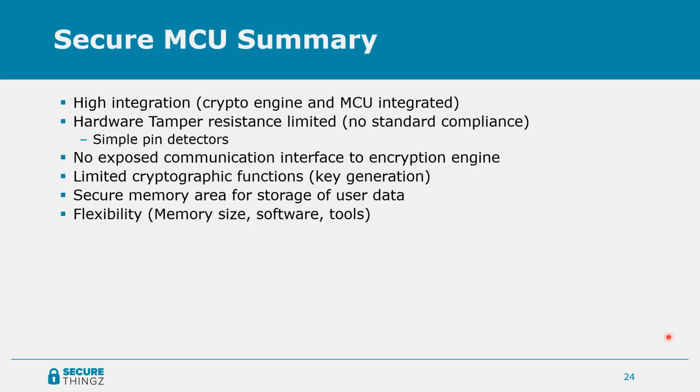There are no exposed communication interfaces because it's all fully integrated in the one package, so you can't see any data. Limited cryptographic functions, so key generation on these devices is often slow and limited. They do have secure memory areas for storage of user data, and of course they're very, very flexible. Lots of memory sizes, software and tools available.